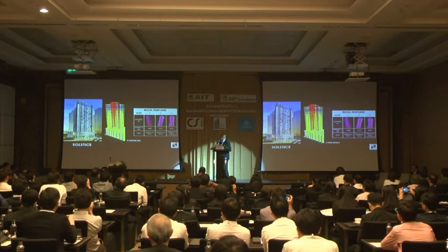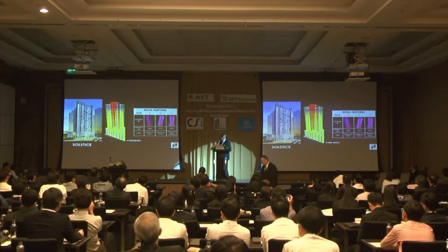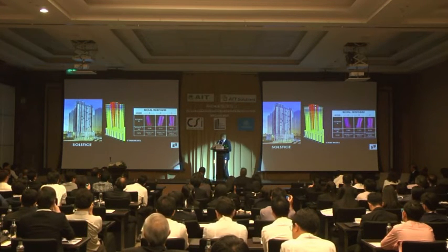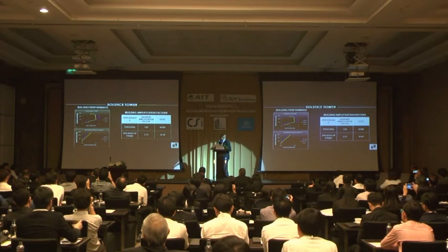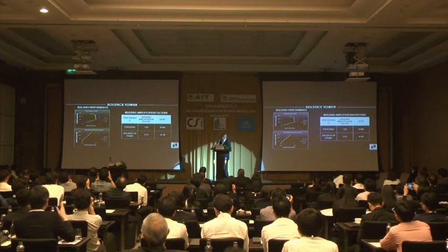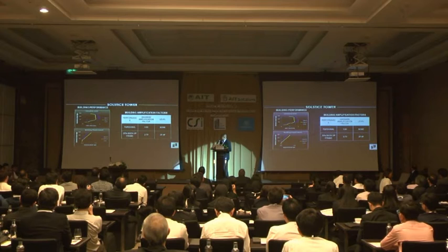So the mode of response for the first two modes are translation, and the third mode will be translation plus rotation. Next, please. The building performance is within the code specified limit, but you have a penalty for 25% backup frame at the second to the fourth floor.